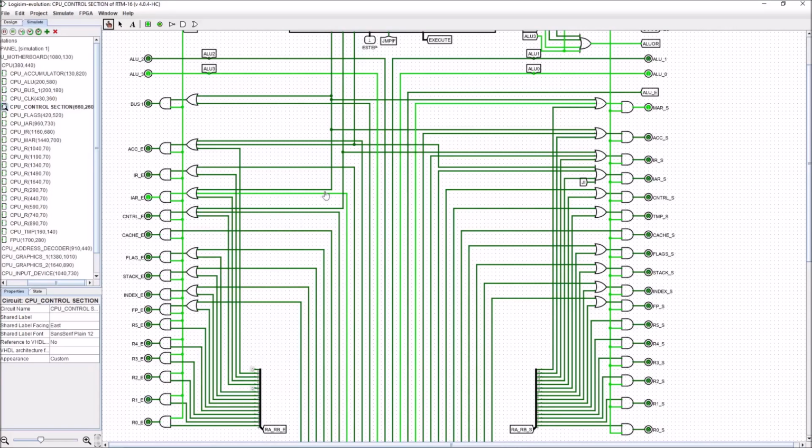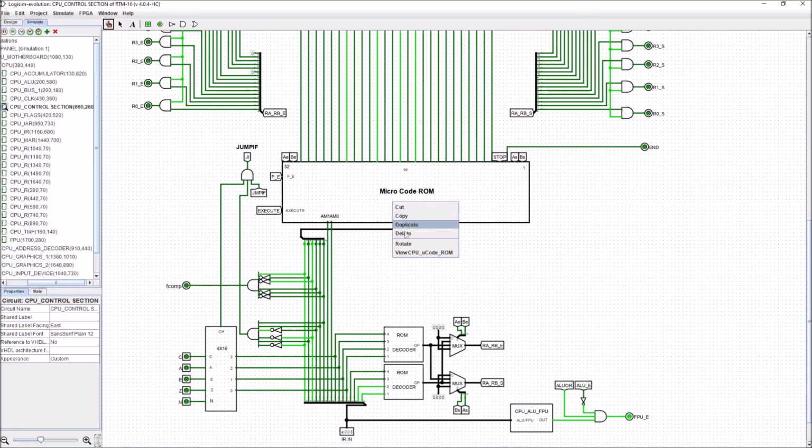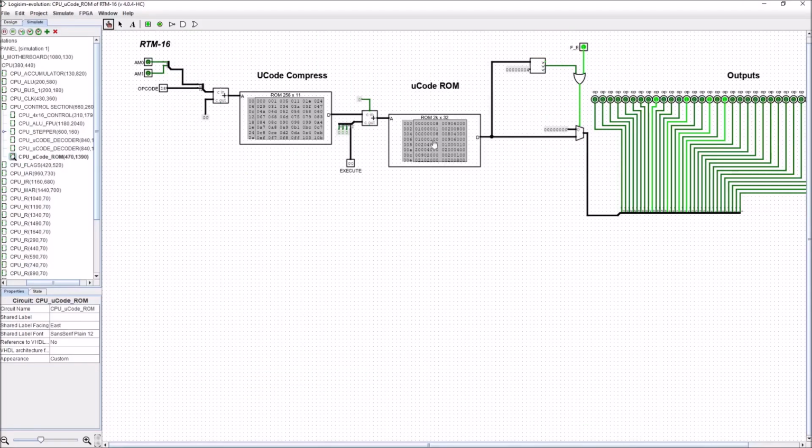instruction address register enabled, the ALU3, ALU0, which in effect is the number 9, which is the reset for the CORDIC unit, and also the memory address register set. So you can see here that these come from our microcoded ROM. So we head into the microcoded ROM. They're coming from within the ROM here. And the first value that comes out is this one. And you can see here, it's just a bunch of zeros and ones coming out along this line here.